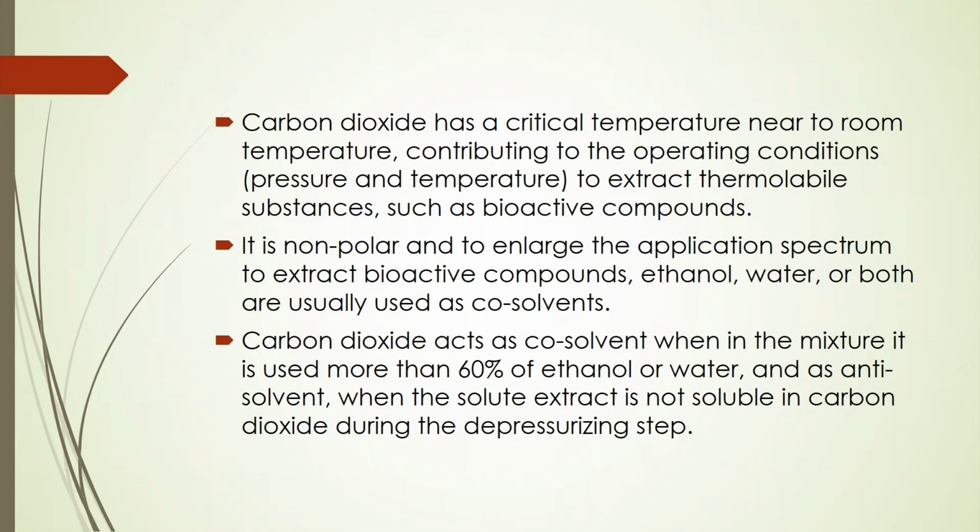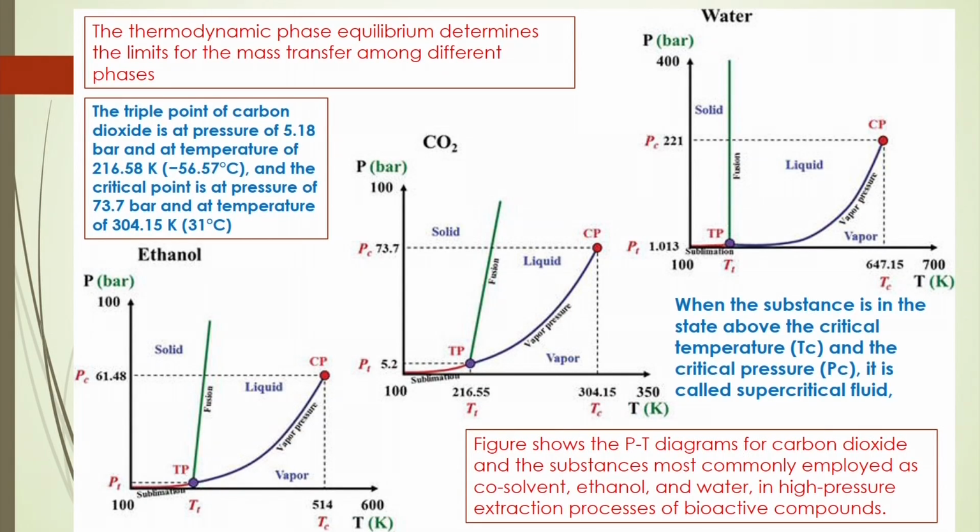It is non-polar, so to enlarge the application spectrum to extract bioactive compounds, ethanol, water or both are usually used as co-solvents. This is the condition at which you can get the supercritical solvent of carbon dioxide. In this case, the thermodynamic phase equilibrium determines the limits for mass transfer among different phases. In these slides, we are showing the different phase equilibrium conditions of ethanol, carbon dioxide and water.